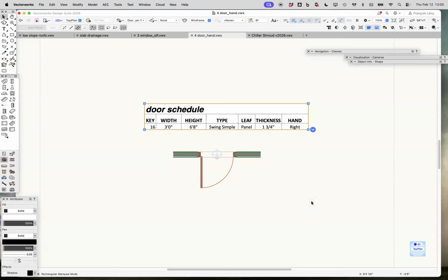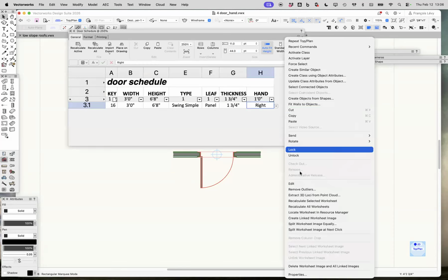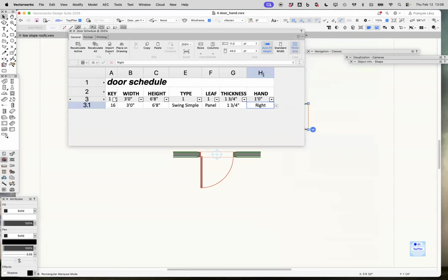I'm always a little afraid to show handing on my schedule. I'd rather somebody else take responsibility for ordering the door. Well, perhaps the door guys will actually have LH, L or whatever. I mean, whether or not it's swinging in or out, in addition to left and right. So yeah, I would avoid it. Yeah, I stopped showing it on my schedule because the different manufacturers call a left a right and a right a left. It depends on whether you're on the push side, the pull side, the latch side, the hinge side. Exactly. Yeah. And it's also different in different countries, right?